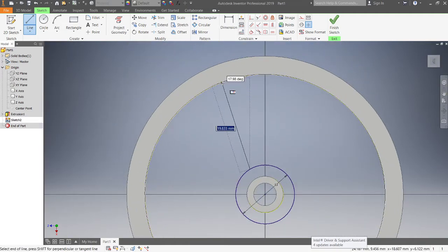And then make sure it snaps at the top so you can see that symbol in between my two dimensions there. If you don't do that, it's still an open drawing, so it means that they will just float and they're not connected, so you won't be able to extrude them. Anything that you extrude has to be connected.